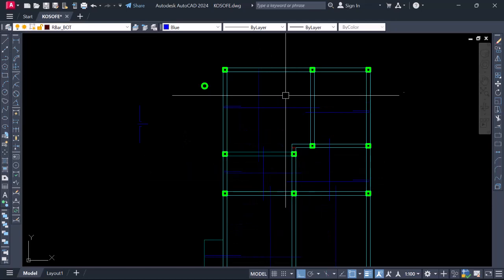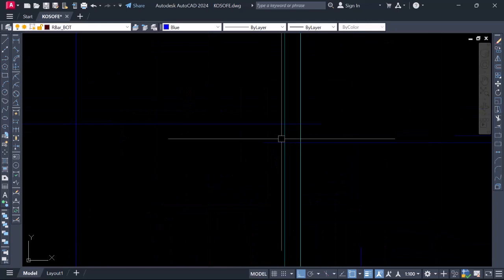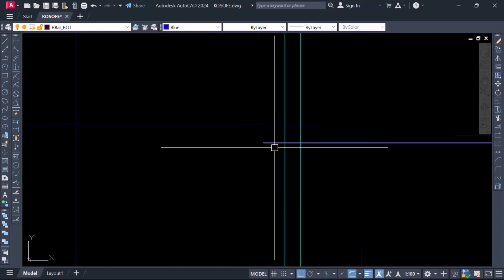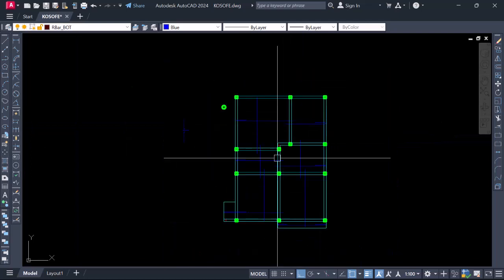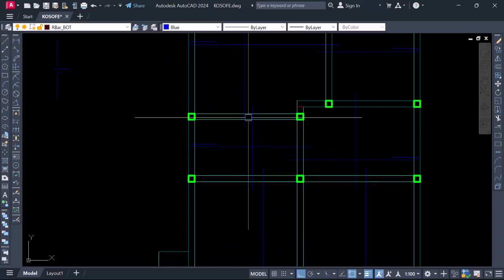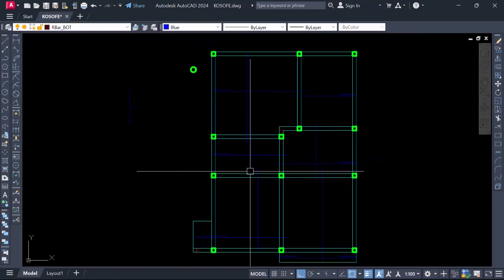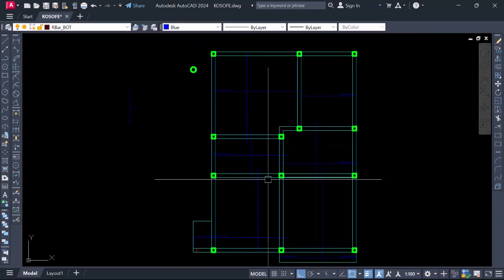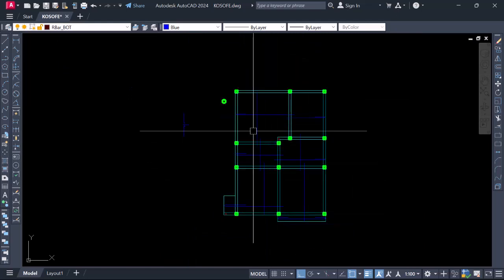But when you have a beam situated like this and there's a need for you to detail it panel by panel, always try to cut the reinforcement across and cut the reinforcement over across. That is very, very good when you're doing that on site. So that is why I have to implement it here in my structural detailing of the slab. So in this regard, we have gone far in our detail.